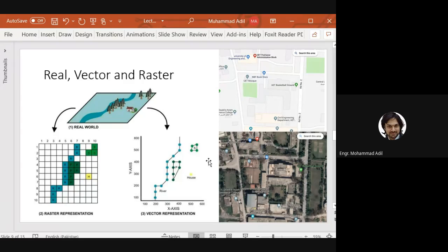Using the polyline or polygon or point tools in AutoCAD or in QGIS software or in any other GIS software where you have georeferenced this image, now you will start drawing polygons on the surroundings. Now automatically all other points you will draw will get coordinates automatically. You don't need their coordinates because this map is georeferenced. It knows all distances and all lengths and all locations. So wherever you will click, now GIS software know the coordinates because this is a georeferenced image. Do you understand what I'm saying?